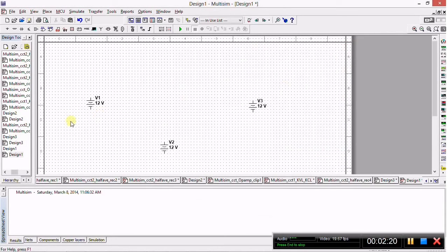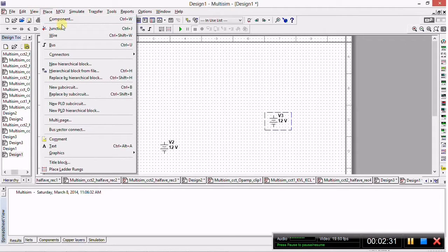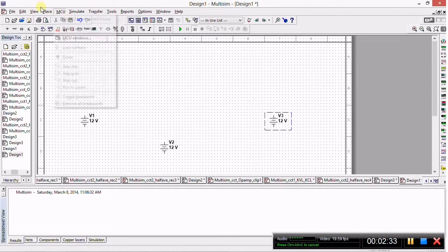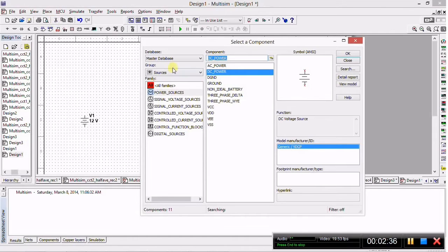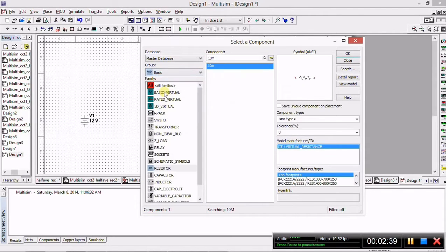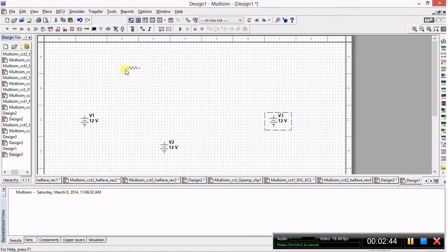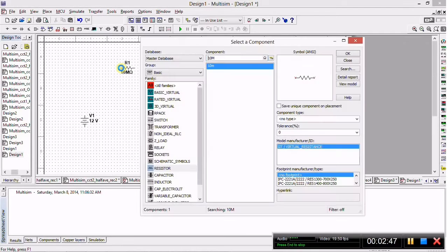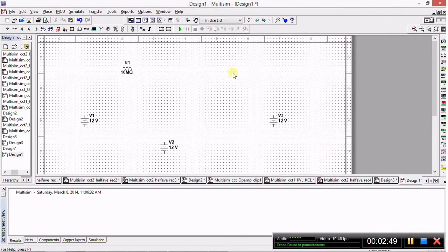Now we can close. We can left click on components and hold down to drag them, so we could move them all over the work area as we see fit. Now we are going to place the 4 resistors. So we go back to place component. This time we go to the basic grouping and we will select resistor. Click OK and place the resistors on the workspace. Keep clicking OK to place all your resistors. And there we have it. We have the 4 resistors needed.